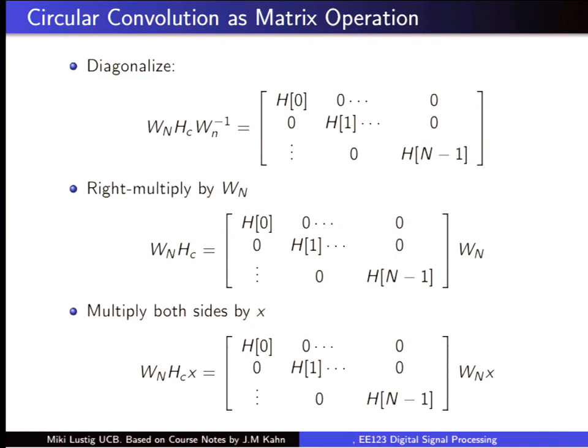It kind of makes sense because whenever you have such structure, it's always a circular filtering operation, always circular convolution. It's just the different coefficients of that operation. So performing a DFT diagonalizes it. If we take the circular matrix and diagonalize it by multiplying with the eigenvectors from the left side and the inverse from the right-hand side, then you'll see that the diagonal are the DFT coefficients, which are also the eigenvalues. That's pretty cool.